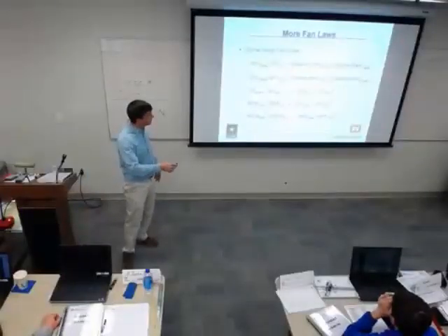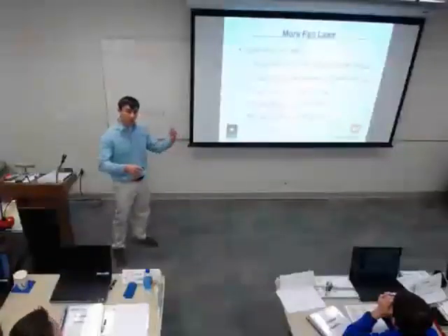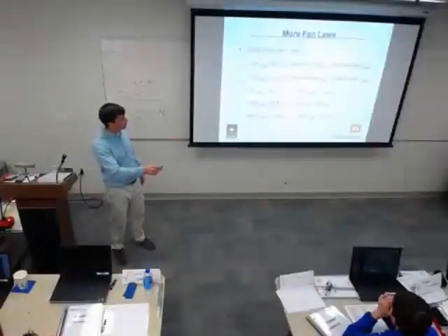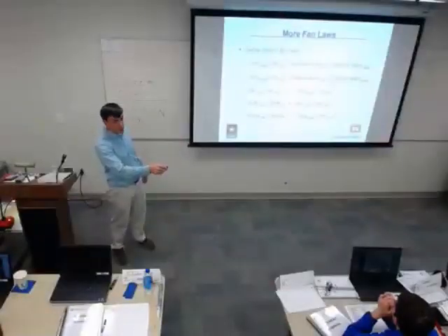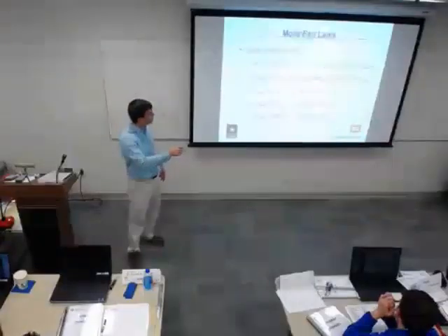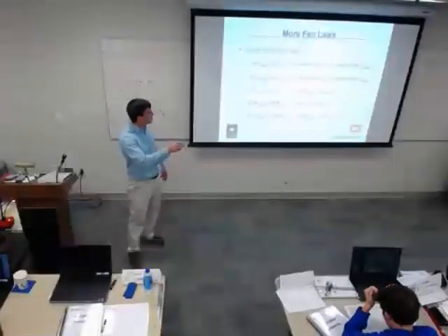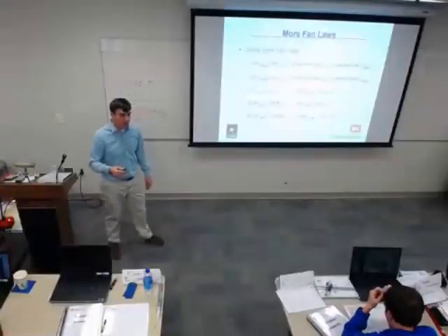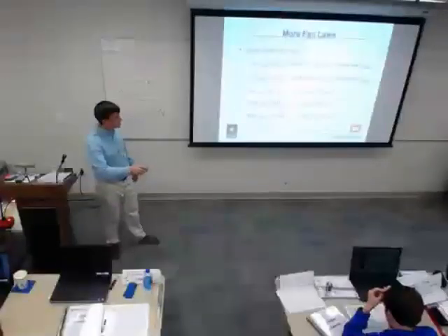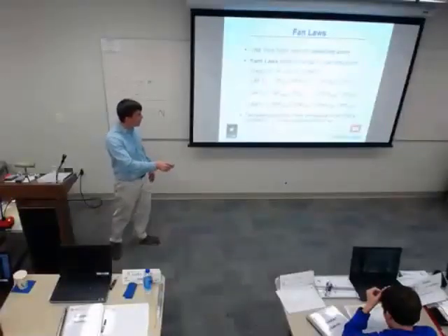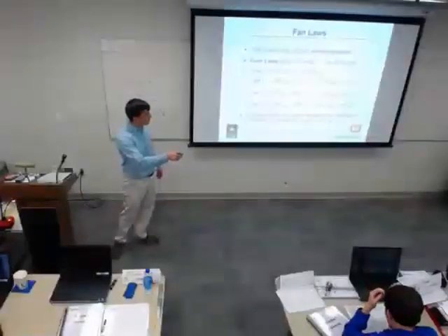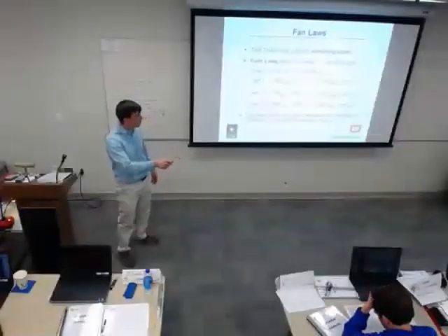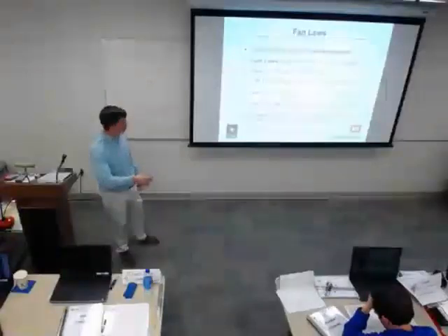This is just rearranging those terms that I just showed you. There's also a linear relationship with the sheave diameter, so you could also put equals RPM over here. And I probably need to do that, but here it is right here. RPM and sheave, CFM and sheave, they're all equal. And I can just substitute terms. On this sheet, the relationship between RPM and static pressure is squared.